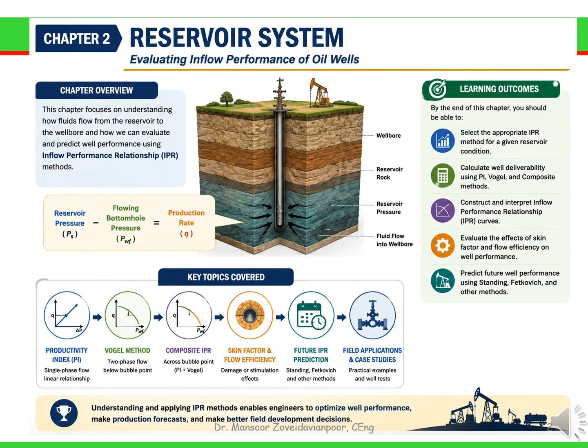Next, we'll investigate the effects of skin factor and flow efficiency on well productivity, learn how to construct and interpret Inflow Performance Relationship, or IPR, curves, and solve practical engineering examples. Finally, we'll explore methods for predicting future well performance and discuss how these techniques are applied in the field.